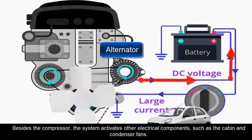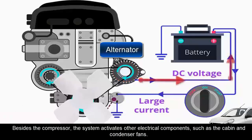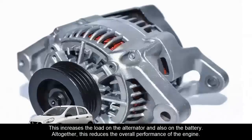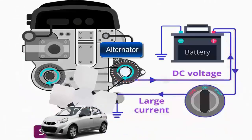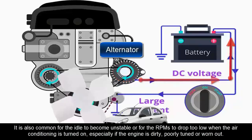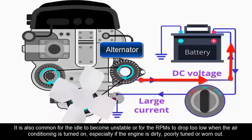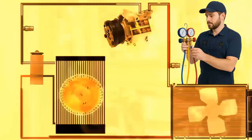Besides the compressor, the system activates other electrical components, such as the cabin and condenser fans. This increases the load on the alternator, and also on the battery. Altogether, this reduces the overall performance of the engine. It is also common for the idle to become unstable, or for the RPMs to drop too low when the air conditioning is turned on, especially if the engine is dirty, poorly tuned, or worn out.